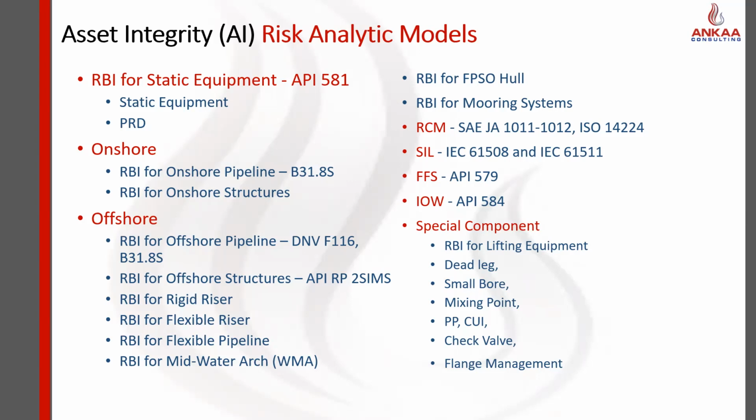And then we've got the methodologies for analytics for each of the specialist components. These are very important because although they are small within the scale of the asset, they are often the bad actors, because of dead legs, where we've got static fluids in there, and they're prone to accelerated damage mechanisms because of that. So you need to have a clear focus on that, and you must have analytics for all of this.